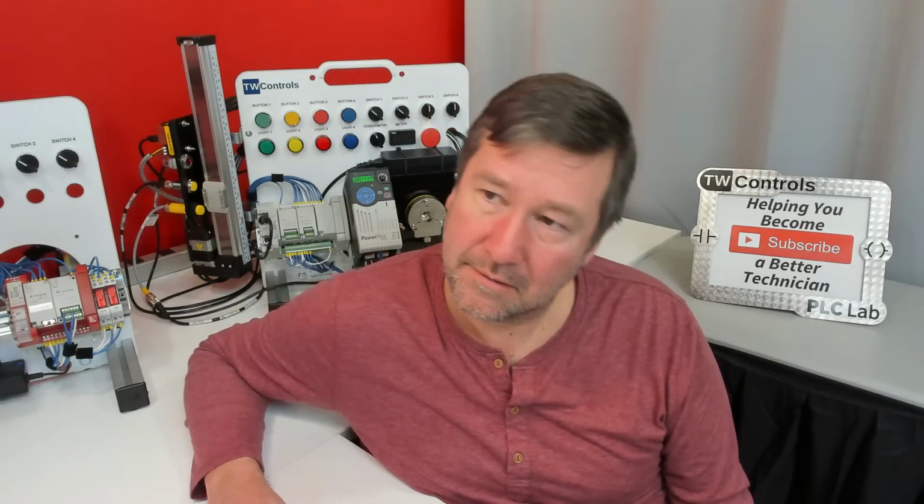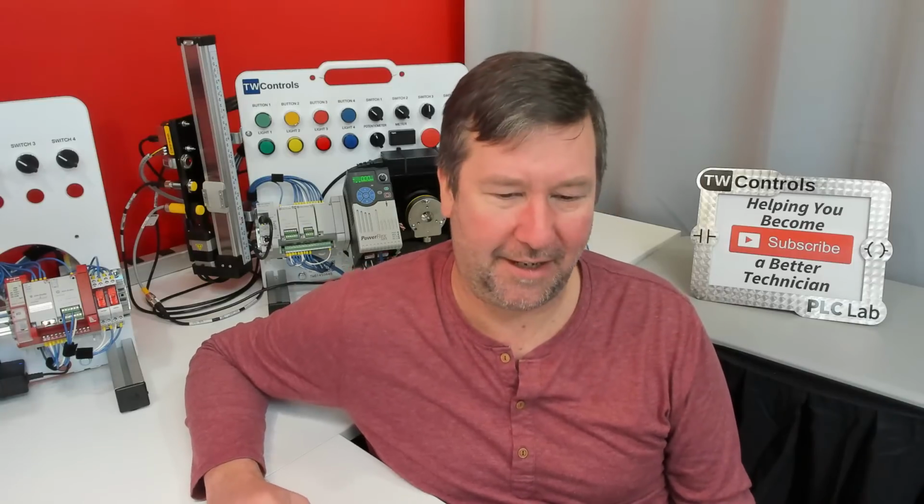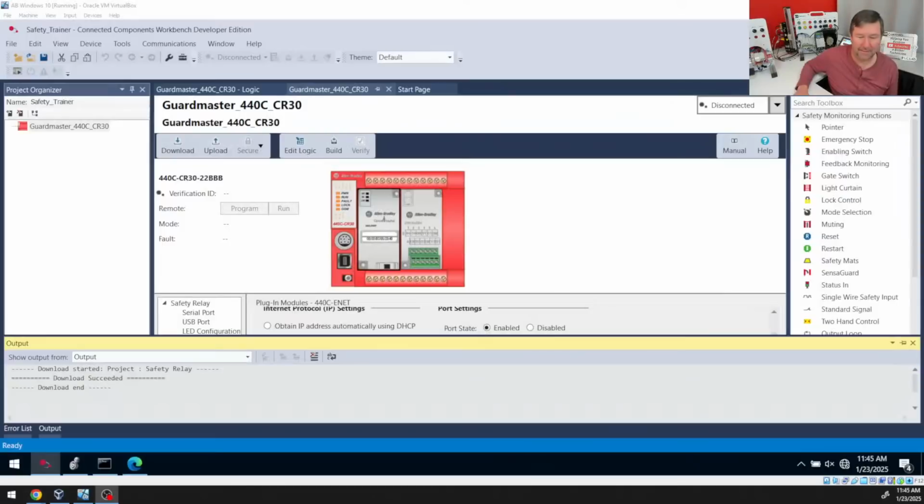Can you provide the Allen Bradley simulator software name for PLC? Yeah, it's in the Connected Components Workbench. If you open up Connected Components, do I have a version? Actually, here you go. Coincidentally, I have Connected Components Workbench open with a configurable safety relay, but right here you have Start the Micro 800 Simulator.